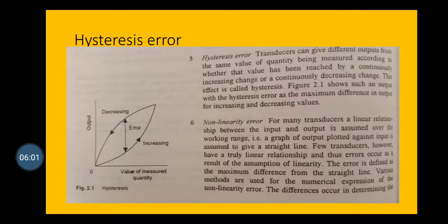This effect is called hysteresis. This figure shows such an output with the hysteresis error as the maximum difference in output for increasing and decreasing values.